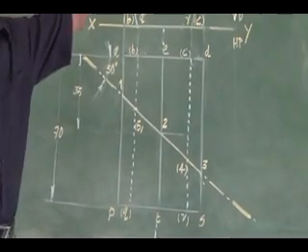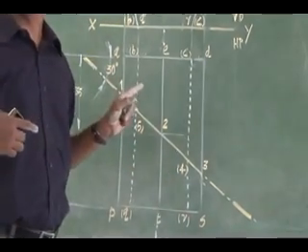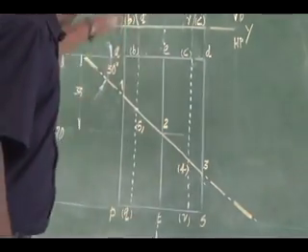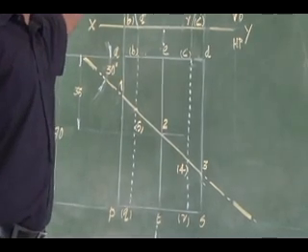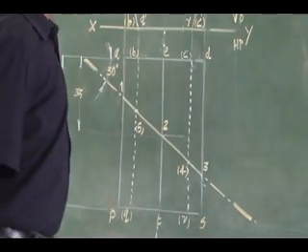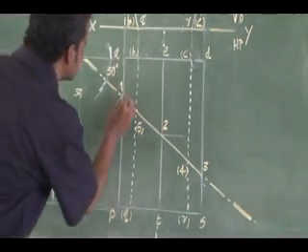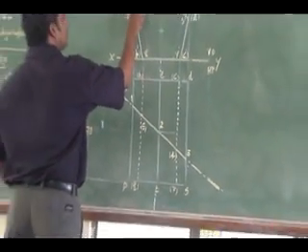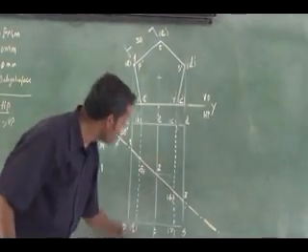Then you project this to the front view. So you look at these cutting points. These cutting points are cutting these side edges. In the front view, where you have the side edge PA, it is seen as a point here. The side edge PA is seen as a point, so my cutting point also will be on that point itself. By projecting this, I will get my cutting point here on the edge itself. Similarly cutting point 2, it is on TE.